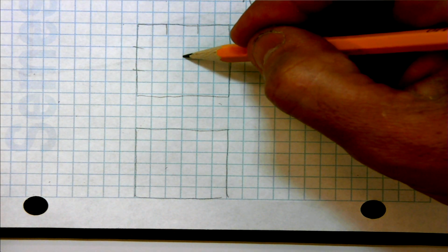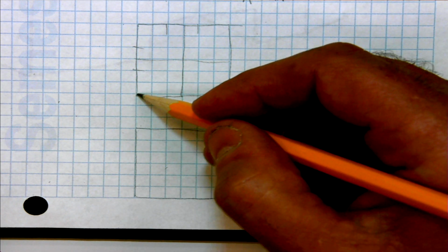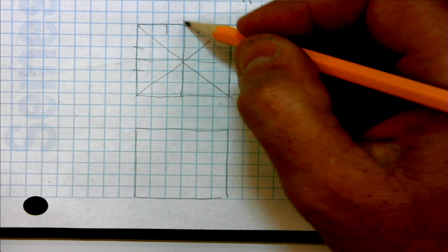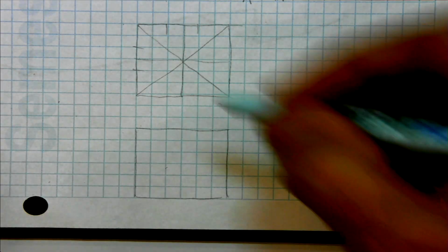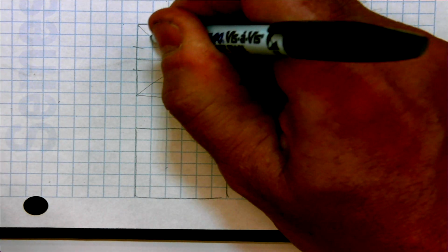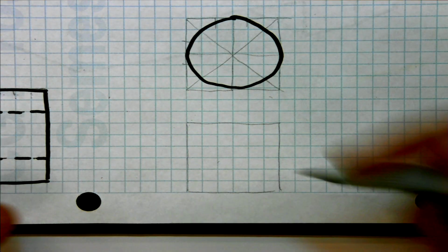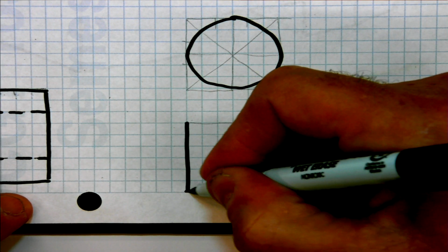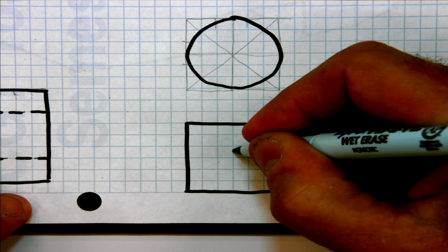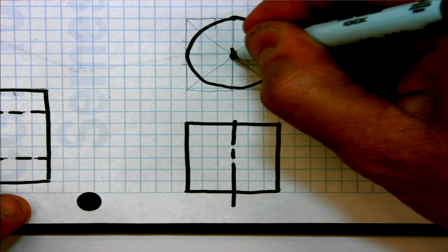Here's my axis. Excuse me, let's put my construction line in here first. With construction lines, you can make circles appear as circles. If you have to, take your time and put in more construction lines, then please do so. I'm going to get really brave here, and I'm going to do this circle right down here first. Let's see if I can do it any better, just quickly. The quicker I do them, typically the better off they are. So again, here to there, back over to here. There's my axis in here, and my axis right here.